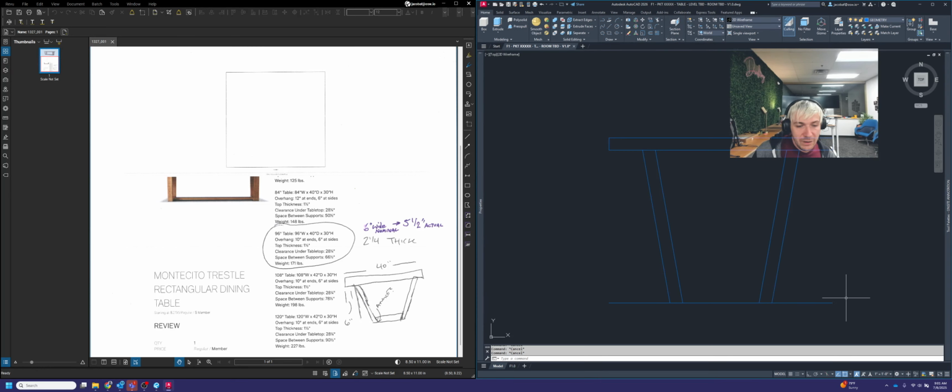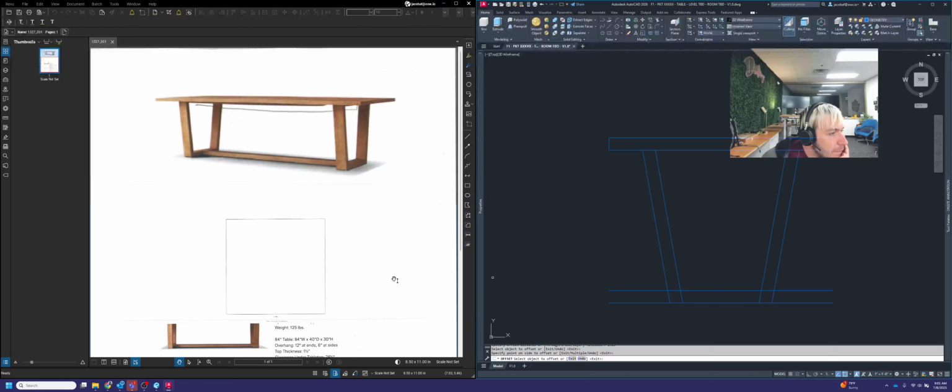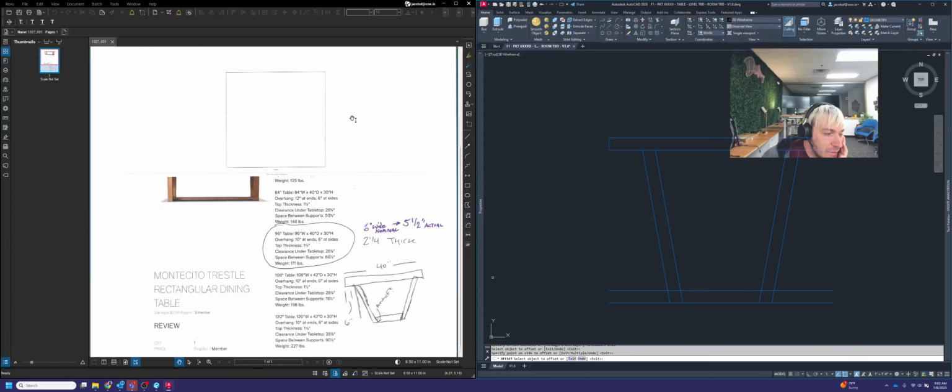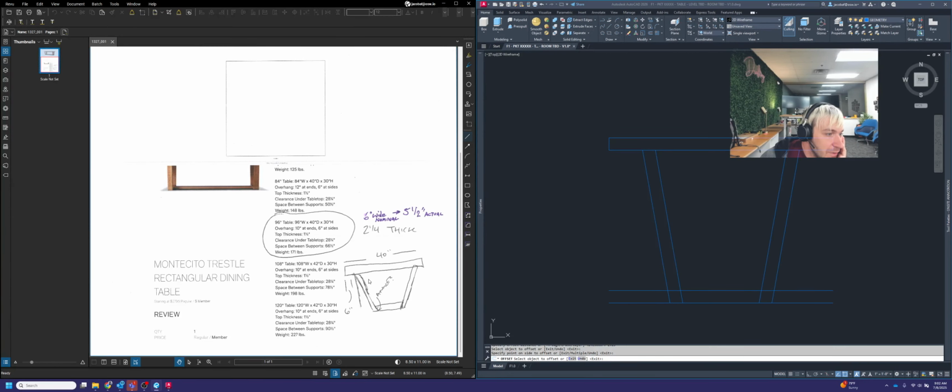All right, so we do still need to offset this line at the floor. We're going to offset this up 2 1/4 to deal with that material thickness just like this. We are also looking at the side of this. Although it's not sketched in this little hand sketch here, there also is a 2 1/4 thick board that sits right below that countertop right there. It's not in the sketch, but we do need to include it as part of our drawing.